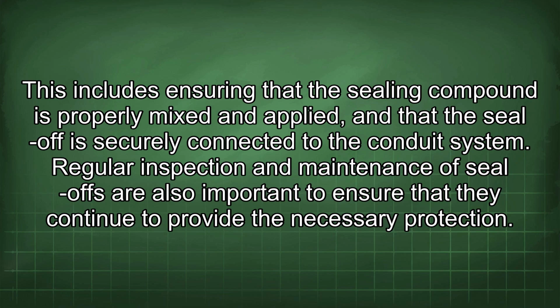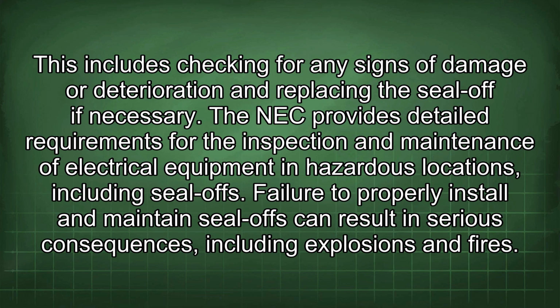This includes ensuring that the sealing compound is properly mixed and applied, and that the seal-off is securely connected to the conduit system. Regular inspection and maintenance of seal-offs are also important to ensure that they continue to provide the necessary protection. This includes checking for any signs of damage or deterioration and replacing the seal-off if necessary.